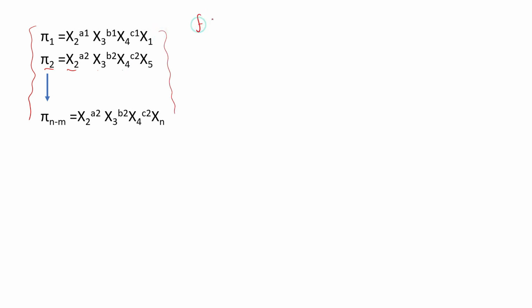That means, in brief, f of x1, x2 up to xn is equal to 0. That is a function of these n variables, and there are m fundamental dimensions. Mostly it is M, L, and T. If temperature is involved, you need to take K. Mostly it is 3. So that means this can be converted to f of pi 1, pi 2, pi 3 up to pi n minus m. The number of pi terms is equal to n minus m.